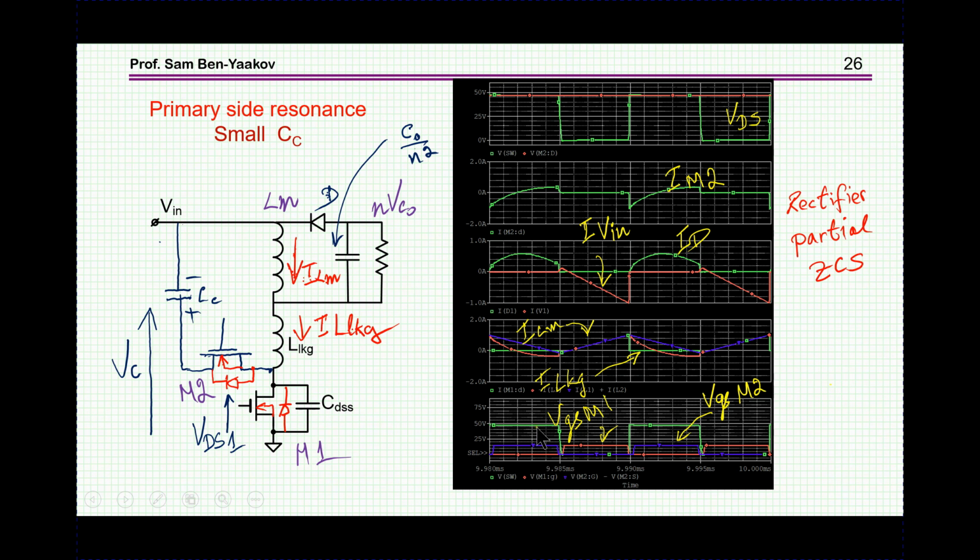And as you can already see here, at the steady state, this portion here, which I was very much worried about, this is the portion of the input current. I'm not showing here the error. This is the positive part of it. This is the current going this way, and it is indeed becoming small. So we are not recycling that much energy because of the curvature of this line. And you can always also see it here. This is the curvature of this current due to the resonance phenomena.